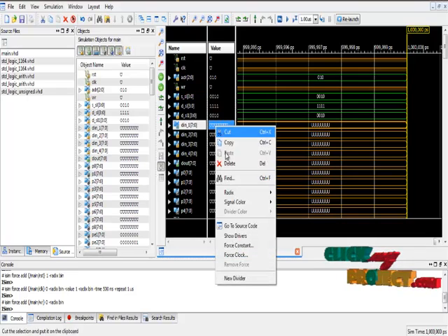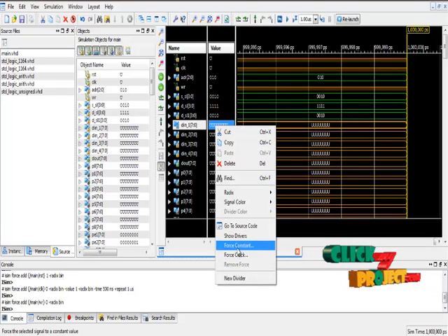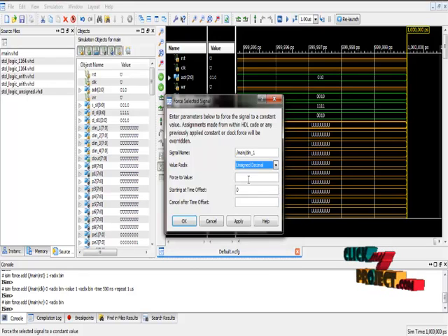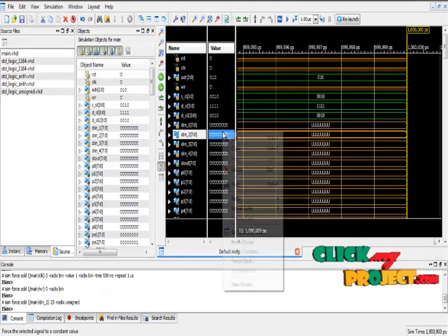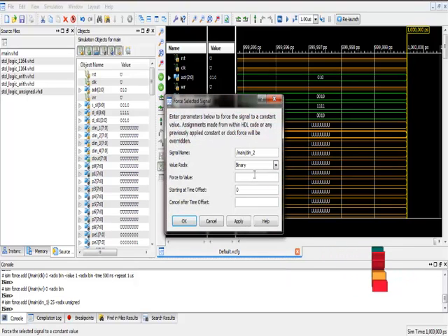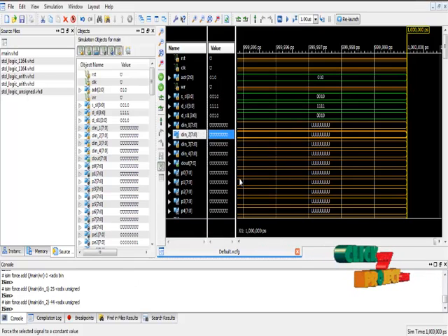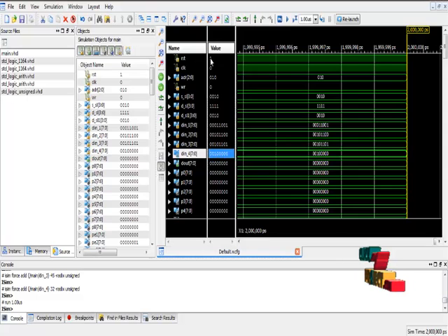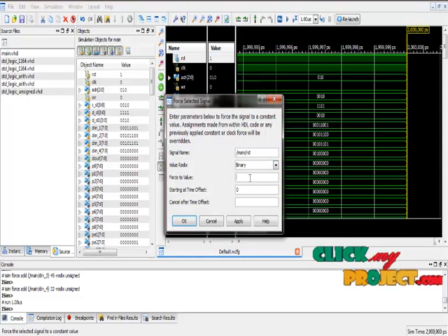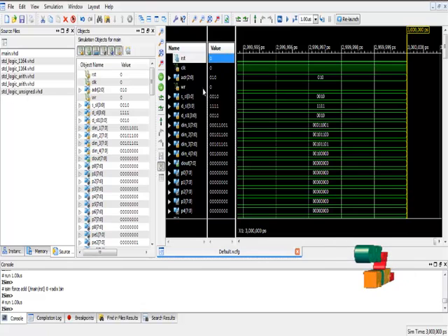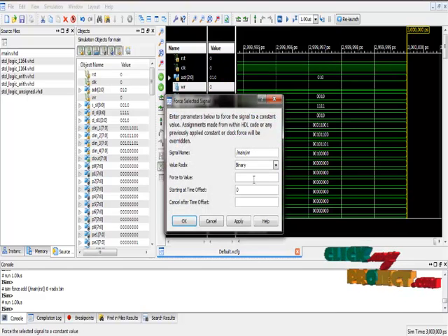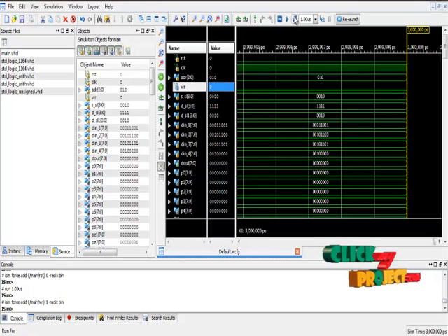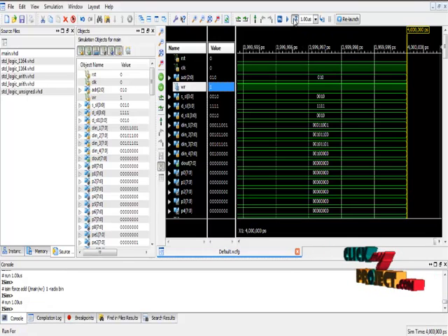Now we give the process for that, with unsigned binary decimal for the same input. After giving all the input, you should run the process. At the same time, we set the reset value to 0 and then run. After that, for the write pin we also give the input 1. So all the inputs are given, and we give the clock pulse 4 times.